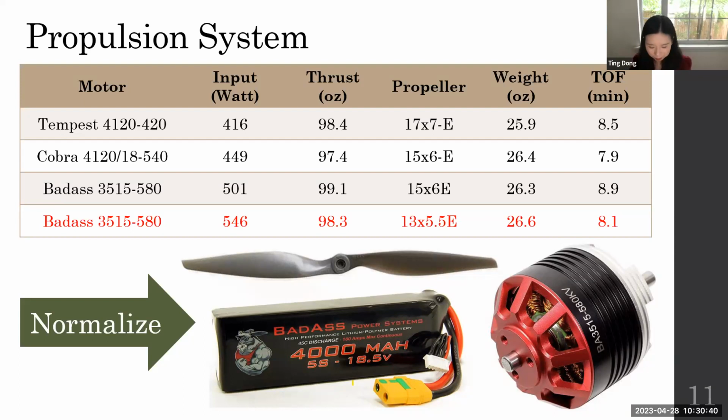Yeah, now I understand. Just make sure that it's clear in the report, because in the report we do need some details. I know there's some constraint for the presentation. I think one of the major benefits of choosing that fourth design was the smaller propeller. As you can see, it's a 13-inch diameter prop. That did allow us to increase our ground clearance, which happened to be a problem on our first test flight. Okay. So in terms of the presentation, you probably should emphasize which one is the main consideration for your decision.